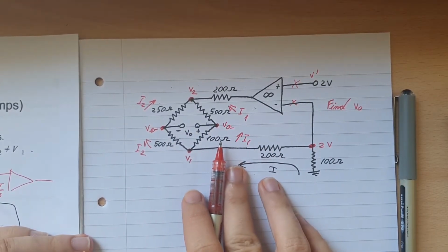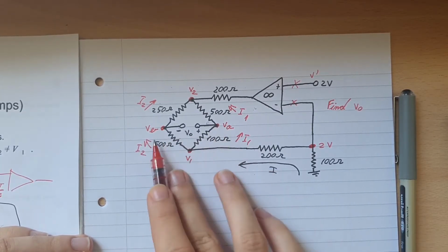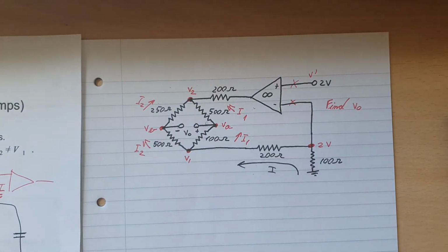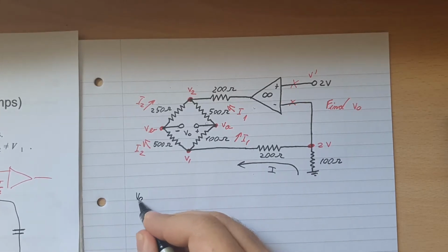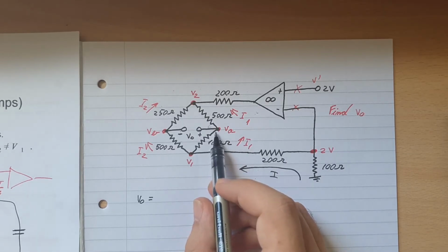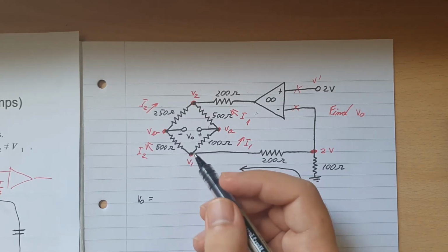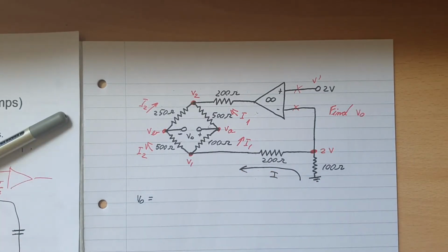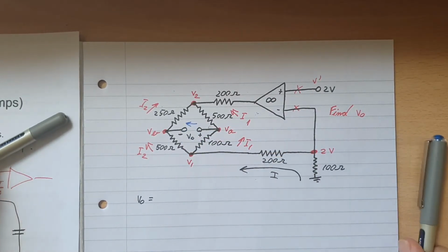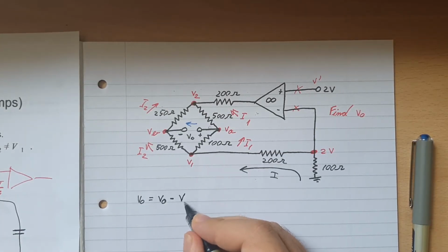So this is everything we can annotate and determine from here. The reason why we need also these two voltages is because theoretically V out will be equal with, we can assume that the current maybe goes in this way, depends. So let's assume, I'll do it in blue, let's assume the current goes in this way, then V out will be equal with VA minus VB.